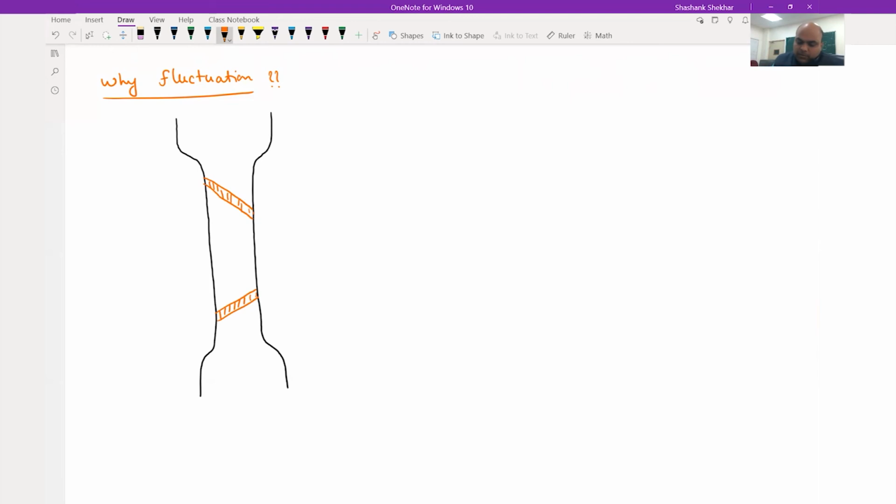Now, if you see this particular region, say I have marked 1 and 1. Okay, both are so initiation of the Lüders bands when you see upper yield point. Okay. Now what will happen? You have generated lots of dislocations in these two regions, both the Lüders bands. Okay. So stresses near that region can go to very high value.